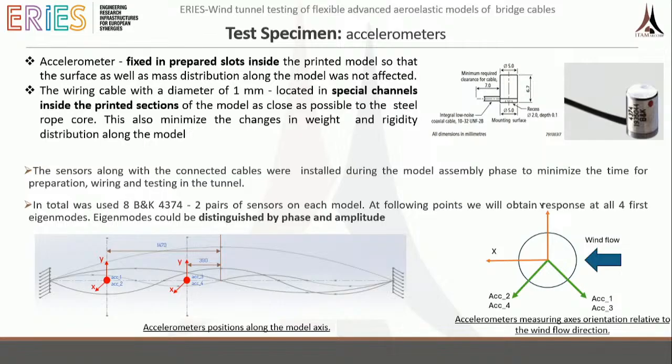Inside of this cable, which was more than 4 meters long, were 4 accelerometers with this scheme, so that we could identify not only the vibration in drag and lift, but also in rotation. And they were these small 2-gram Brüel & Kjær accelerometers.